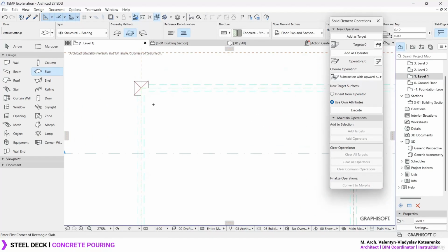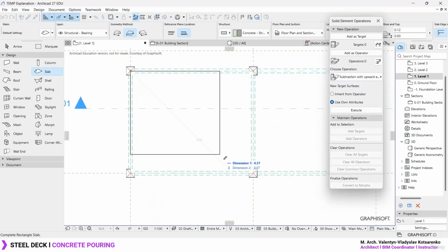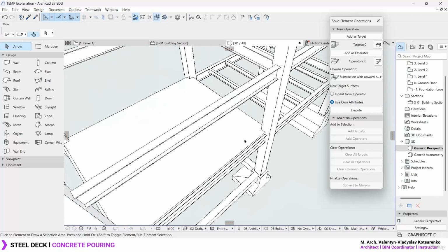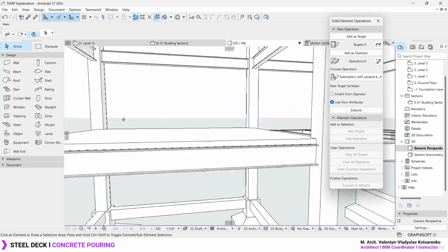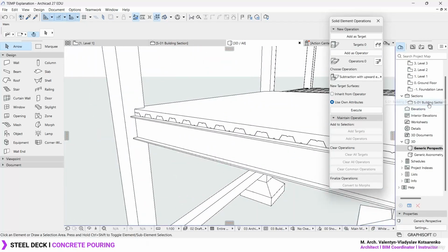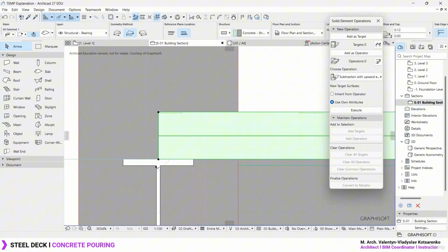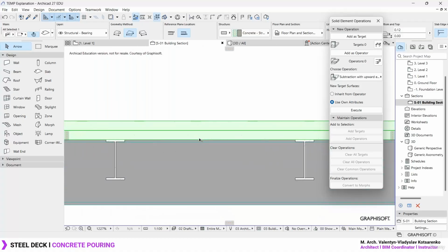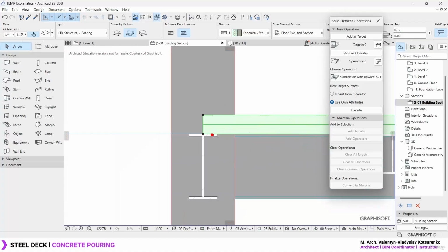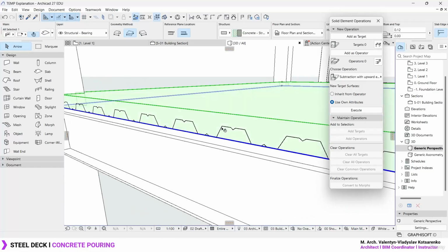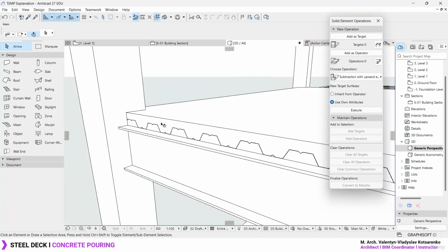Let's press OK. Let's cover once again the whole area with just a basic slab, which is going to be of concrete. And in this case, let's see in a cut section if the slab is positioned correctly. So yeah, it's completely positioned correctly, right on top of the beams. Okay, so having done this, let's go ahead once again. Be careful how you select your objects.